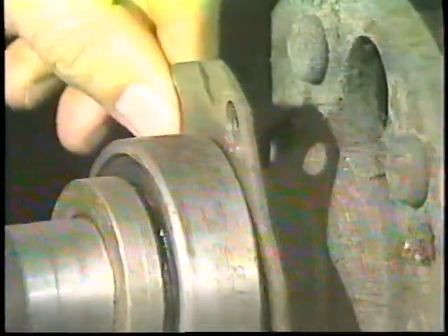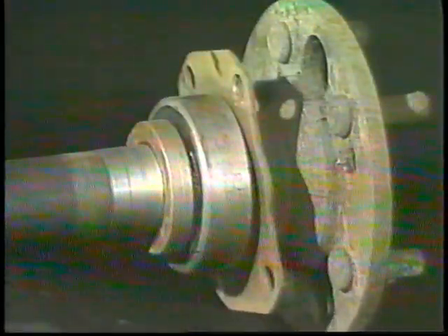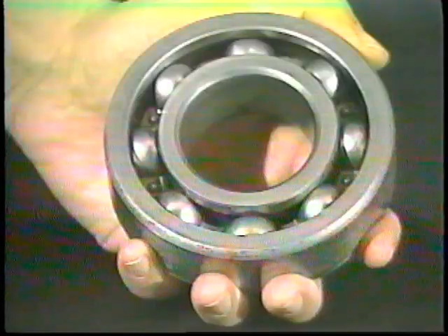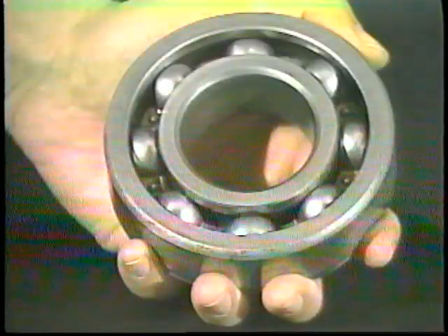Keep in mind that some bearings, once installed, cannot be removed without destroying them. So always make sure that any retainer, seal, or shield that must go on the shaft behind the bearing is actually on the shaft before the bearing is installed. The bore or the shaft must be clean and free of any nicks, burrs, and slivers of metal which could become wedged in the chamfer at the edge of the bearing rings.